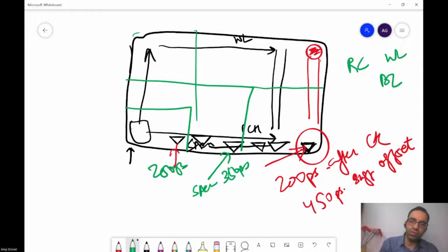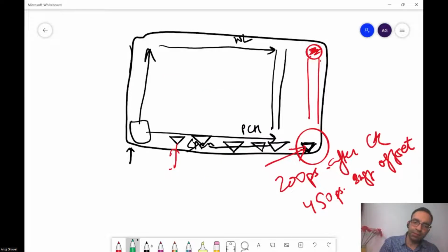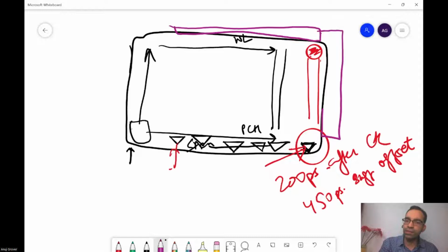So to be able to do this, what you do is you create what is called a replica path. Now, what is a replica path? A replica path is an additional word line and an additional bit line at the end of it. So come to think of it, this word line, replica word line and replica bit line,